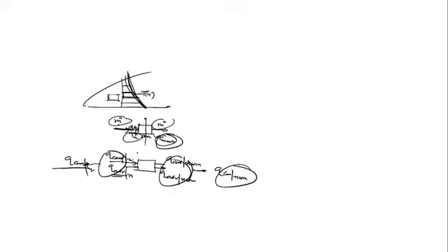What about the y direction? Same thing here. But let's say I'm talking about one-dimensional flow. One dimension means there is no flow in this direction, no bulk flow in this direction. Bulk flow is only in the x direction. Am I right? If there is no bulk flow in this direction, then the heat transfer in that direction is only because of conduction.